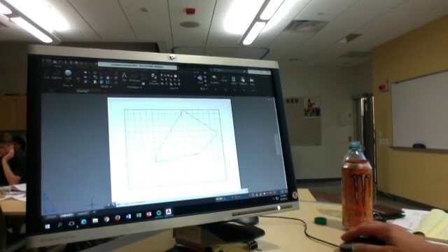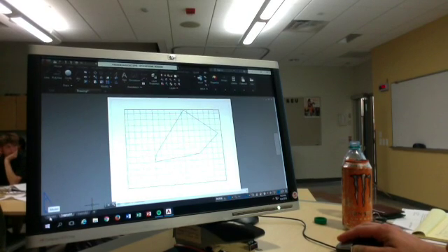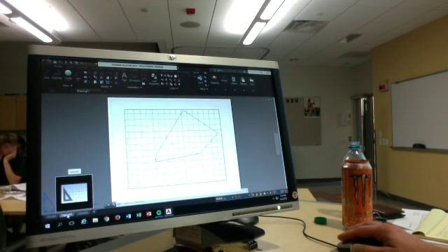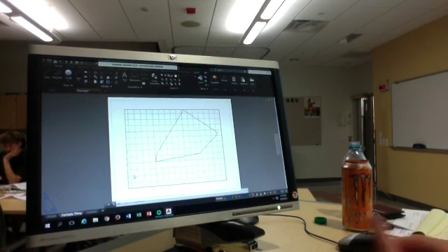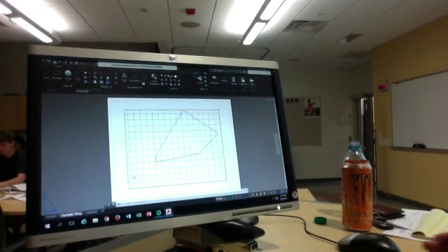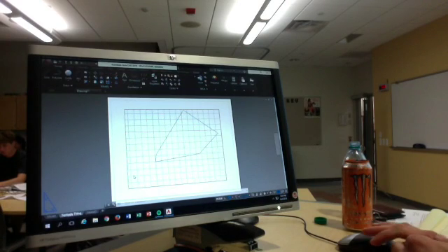Model space is always called model space. It's always going to be the same thing. What's cool about the layouts, though, is that you can change the name of it. You double-click on it. I'll put my squiggly thing. I know I gave it a silly name, but that's actually really important because it determines the sheet name.